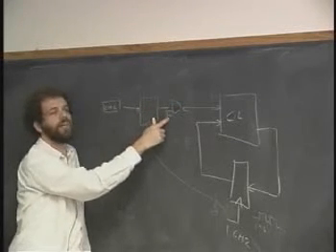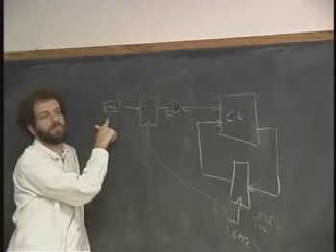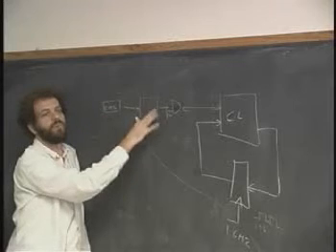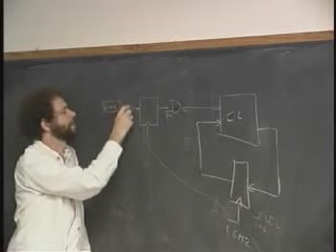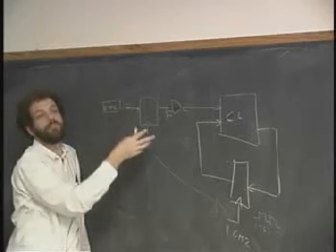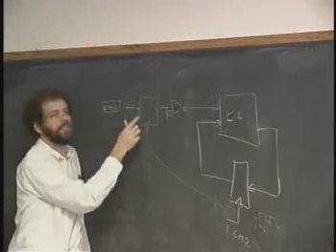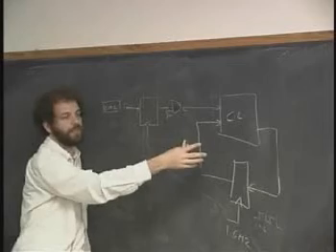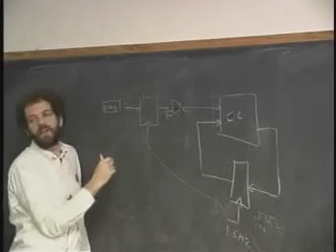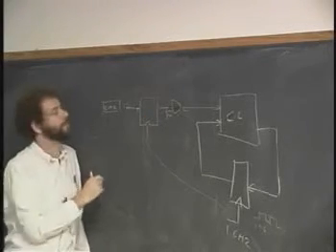So I could turn this off for 100 clock cycles after the person has pressed the button to wait for this to happen. And I could put a gate in here to not allow new button presses to come in during that time. So I could set this off, and it could think about something else for 100 clock cycles, and then I can look at the output. That's a viable way to do it.